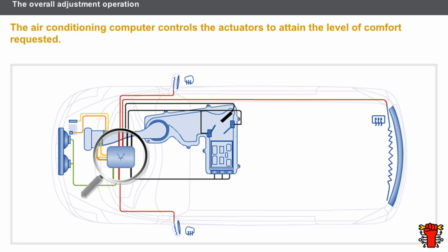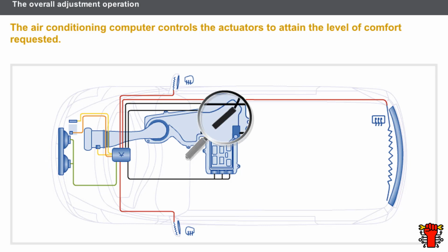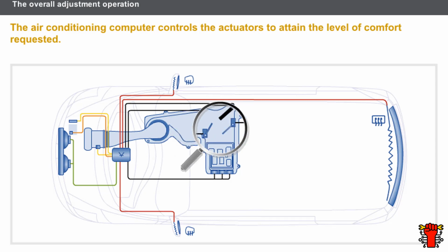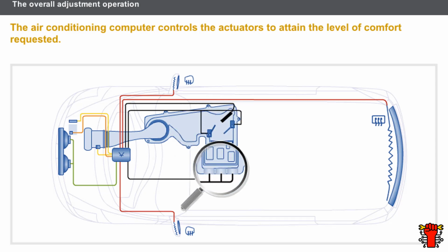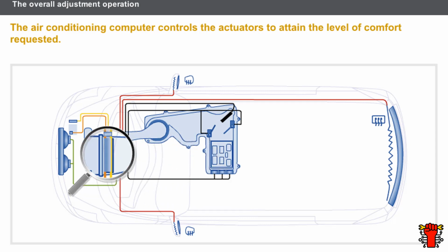These actuators are as follows: the compressor electromagnetic clutch, the compressor electric control valve, the cooling fan assembly, the passenger compartment heating resistors, the rear screen and de-icing rear view mirrors, the passenger compartment fan, the distribution components, the division components, and the recirculation components.